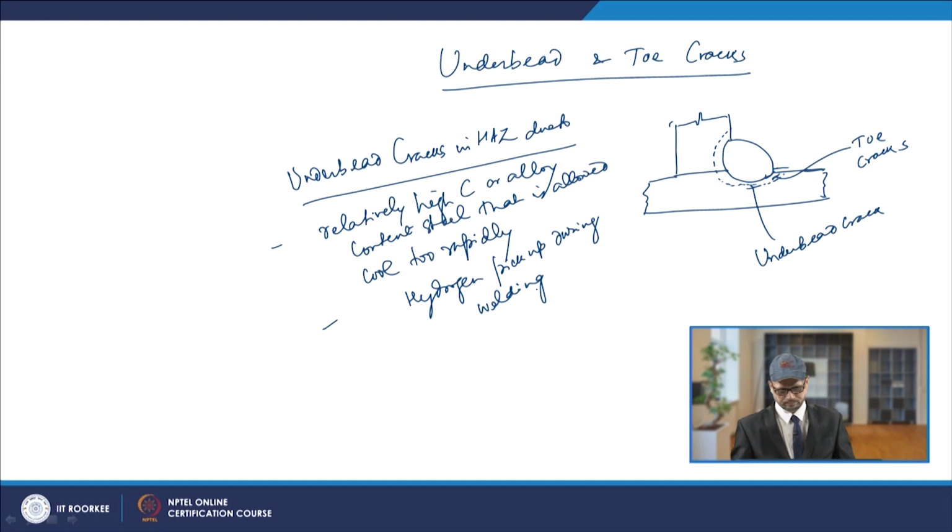Another factor which promotes underbead cracking, so one is the relatively high carbon or alloy content, and another is the hydrogen pickup, that is, pickup and retention of the hydrogen. If it is retained, in those cases you have these chances.